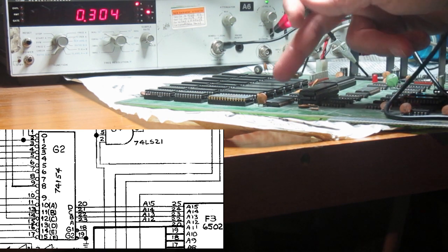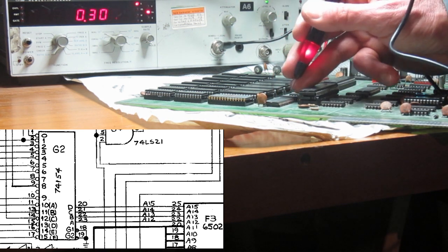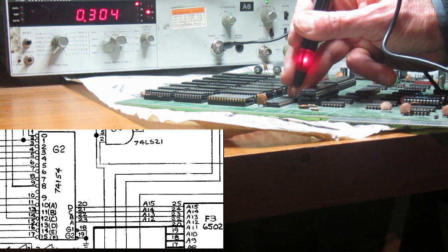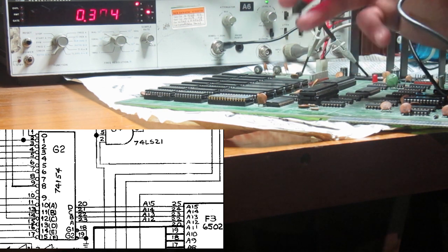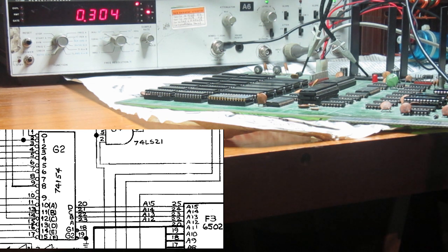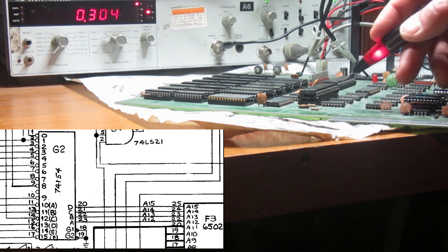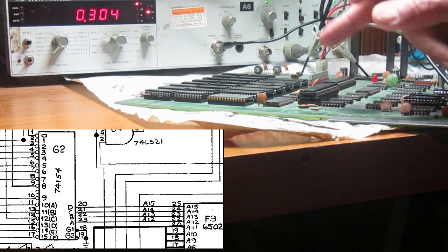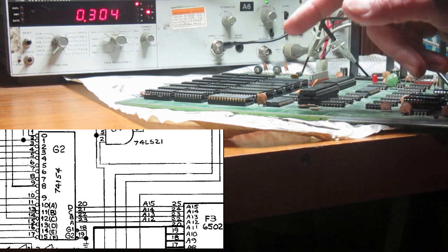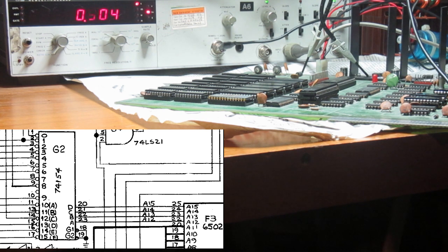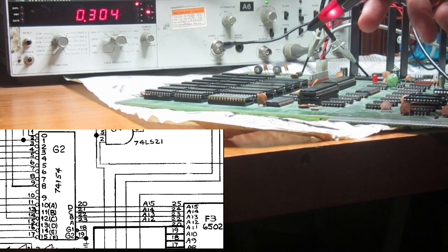Well, I know the board is working, so every output is actually toggling. Okay, just find another one, and it's toggling too. So okay, that's what you can check on a board. If you find a stuck output on a buffer, or an address decoder not giving an output toggling, well, you have found a problem on a board.